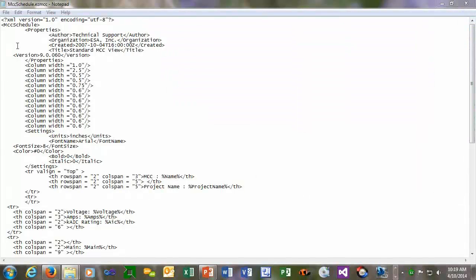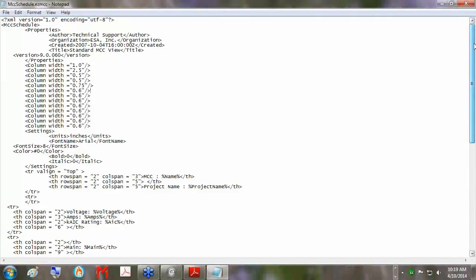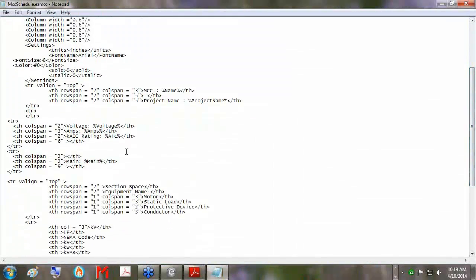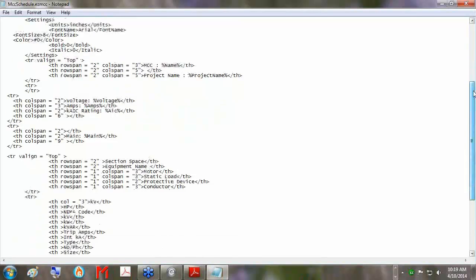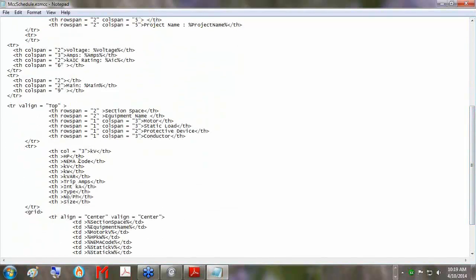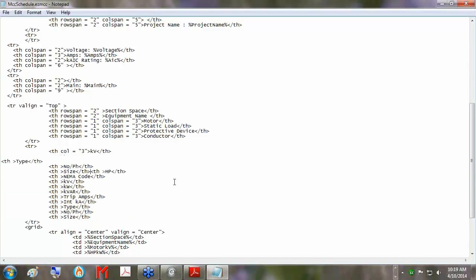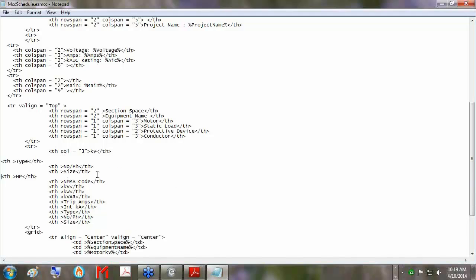So there are some settings, properties that exist within the grid. If you want to come in here and edit it and include or exclude different types of information, you just come in here. Let's say we want to get rid of or rearrange some of the information. We would say select these 3 items and move them to the top of the list. We can copy those and just paste them under the column settings, and you can keep it clean.